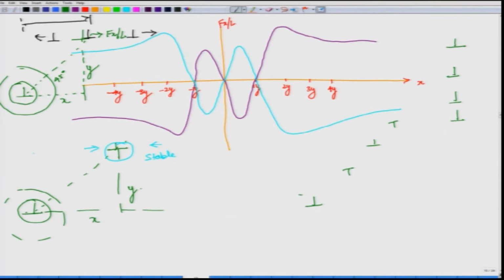We were able to derive the force values, and then simplify it for a pair of dislocations, where one of them is creating the stress and the other is the one the stress is acting on. By taking a little more simplification, without loss of generality, that the line vector is along 0 0 1, while the Burgers vector is only along b 0 0, we are able to get such a simple relation from which we can directly plot these force values, and see what will be a stable configuration when you have all dislocations of the same type.